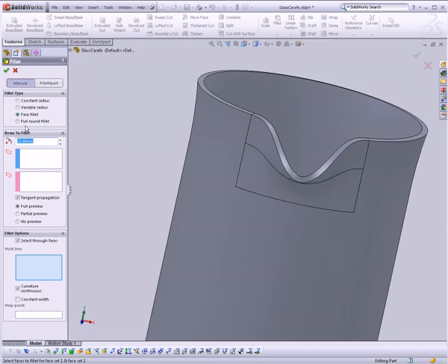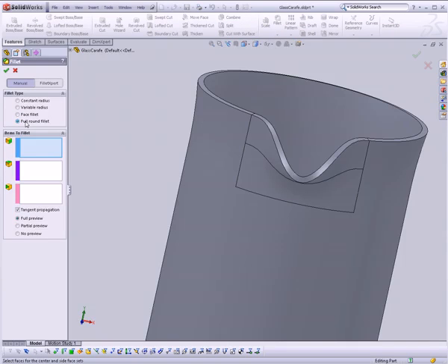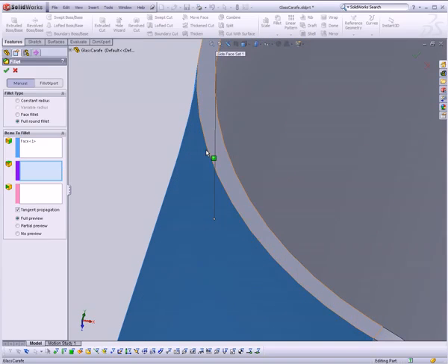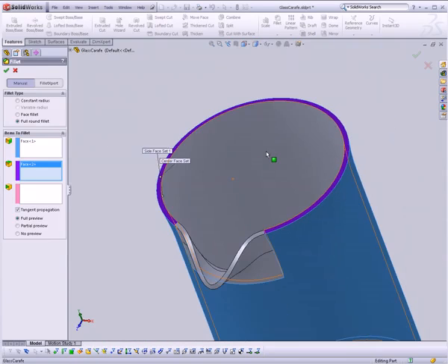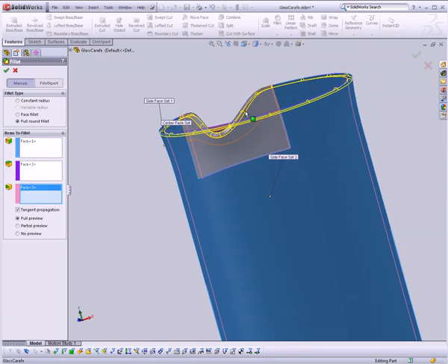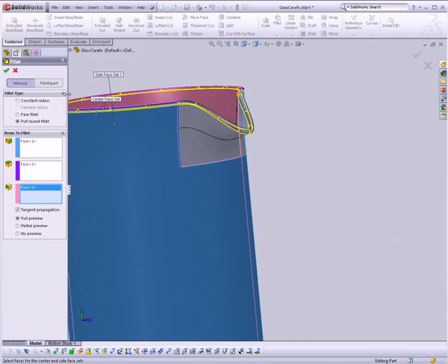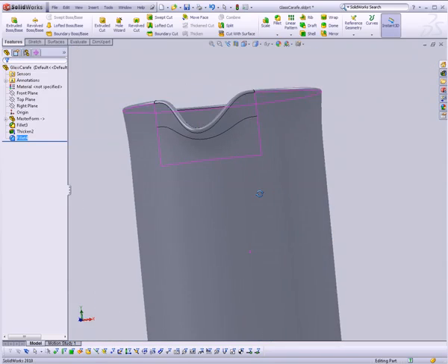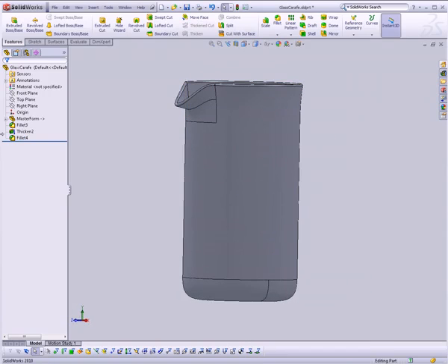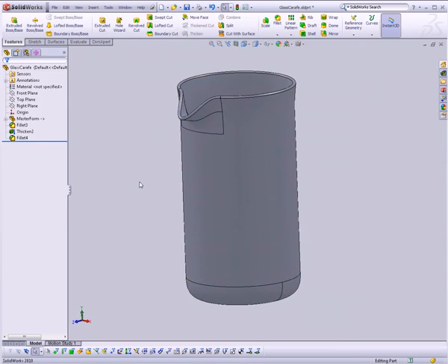Let's go fillet. And this time, instead of face fillet, let's do full round fillet. I'll choose the outer surface for the blue box, choose the top surface for the purple box, and the inner surface for the pink box. And that's just going to do a full round between those three surfaces and propagate that across all tangent edges. Well, tangent faces, I guess, technically. And there we have it. Here is our glass carafe. And if I want to, well, actually, I'm just going to leave this the way it is.